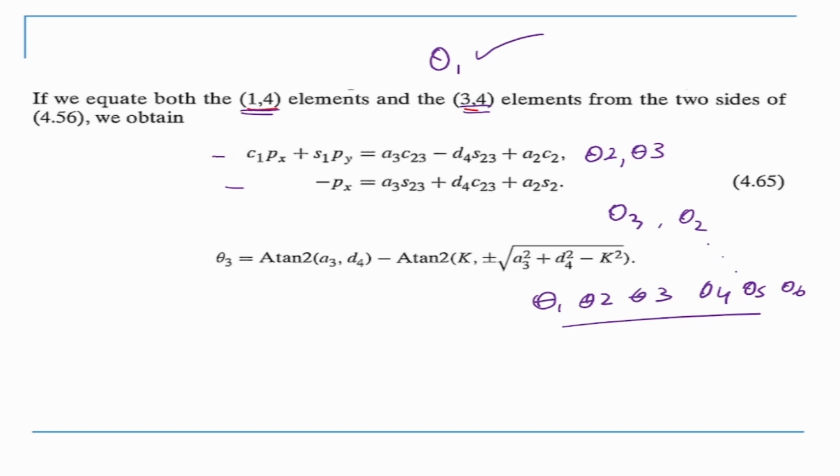Now I am not going to go any more into details of this. We are not required to do inverse kinematics in this course, but when we do the robot programming in the end, on the industrial robot, the robot controller already knows the inverse kinematic solution, and we just have to figure out which solution it is going to take. If there are 6 solutions, it will take an energy optimal solution, the one nearest to the previous solution.